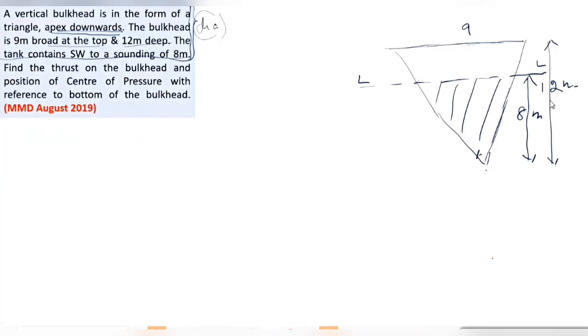Now, beta, if I have to get the immersed area, which is triangular in shape, I'm marking it in red here. I need to know its base and height. Height I know, 8 meters. I need to calculate this base x. Yes or no, beta? Yes, sir. How do I get x? I have two triangles. One big triangle, other is small triangle. They are similar triangles. Why are they similar? Because this angle is common to them. This angle is equal to this one, is equal to this one. They are corresponding angles of parallel lines. So the triangles are similar by angle property.